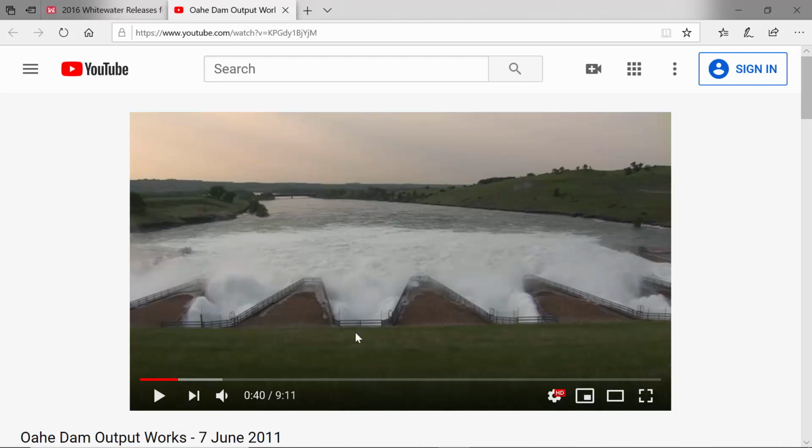So the water is exiting with a really high velocity. It's coming out of those pipes at a velocity that we'll calculate in just a moment, high enough that it would definitely scour a natural earth-lined channel downstream. And so they somehow have to dissipate the energy that's coming out with such velocity and get the water to slow down and have as much turbulence occur close to the dam as possible, because they would typically have a reinforced channel for some distance away from the dam, and then it just goes back to the natural channel.